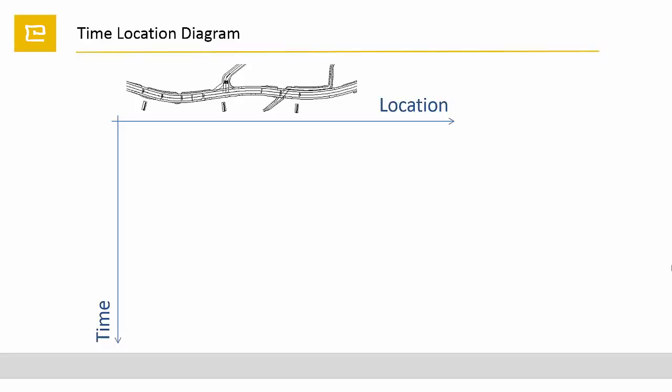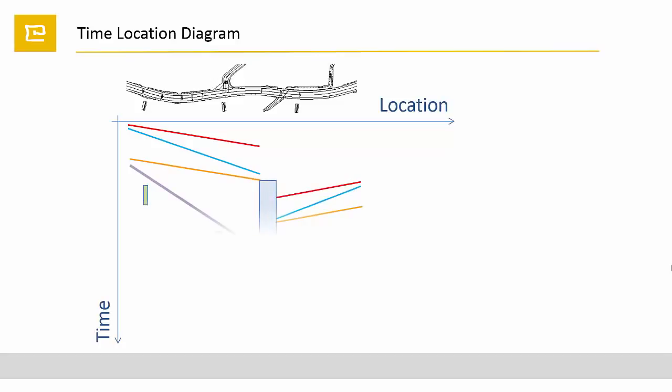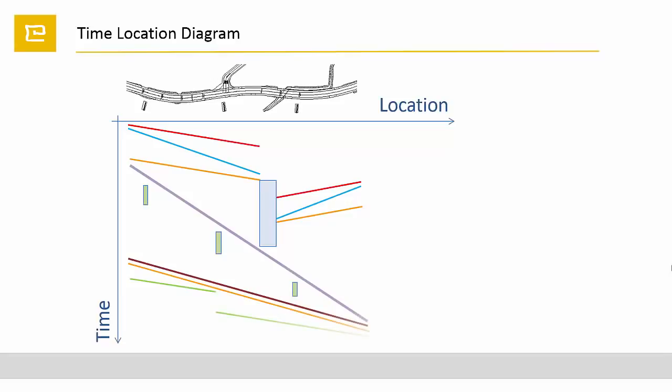This little animation is to explain the idea of planning in a time-location diagram. While time elapses, you see different activities developing on different locations. The lines are moving activities, while the rectangles are just working on a static location. You can see different locations under work at the same time and also activities with different speeds and directions.